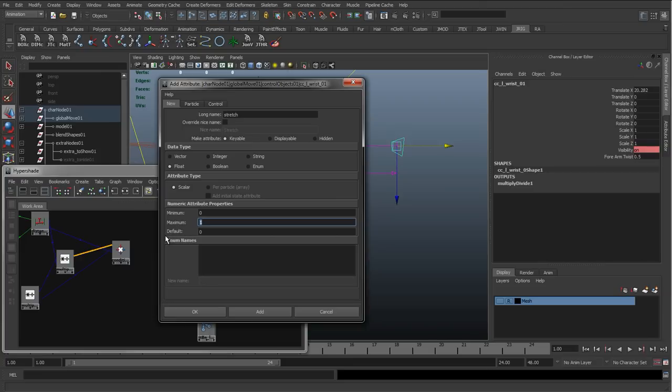You usually just want to turn it on or off, and by keeping it at 1, that means I can usually use that 1 value to drive things like the visibility of objects. So the IK/FK switch, we kept that to 0 or 1, and we could use that 1 to drive the visibility of objects, because the visibility is either 0 or 1, or the weights of orient constraints are 0 or 1. If I'd set this to 10, I'd then have to set up everything as set driven keys. So I just prefer, if I can, keeping this as 0 to 1, so I can use that direct connection. But you can keep this as 10 if you want, or 100 for 100%. It's up to you, but I'm just going to keep this as 0 or 1.